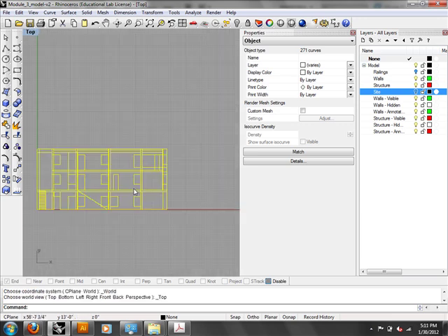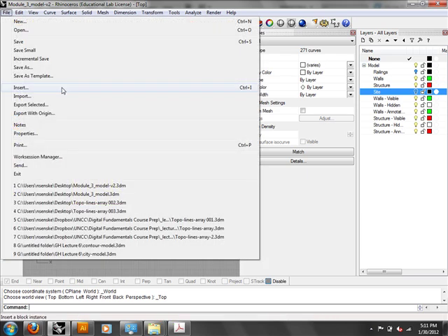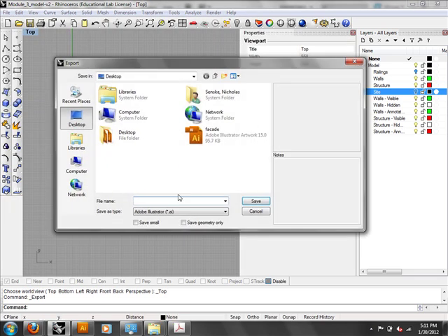The export visible, that's not scaled, right? None. It's never really scaled unless you say that it's scaled. But the thing is, you don't want a 300-foot Illustrator file. Right. You also want to be sure that all your orthographics are the same scale. Yeah, and I'll talk about how to do that in a second. So I did Make 2D on this one, and I can export selected. Let's just call this one facade 2. Just see the difference here.